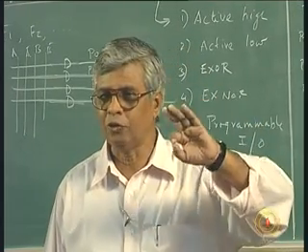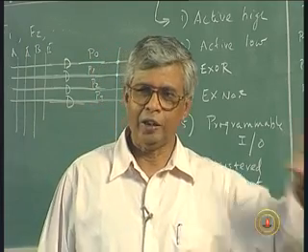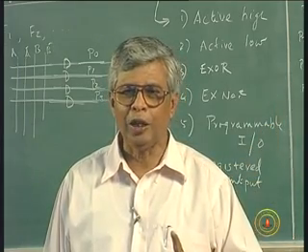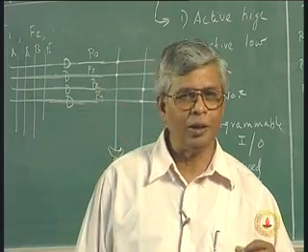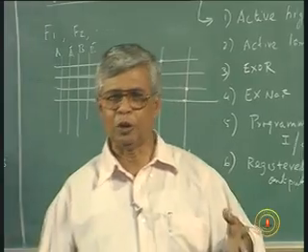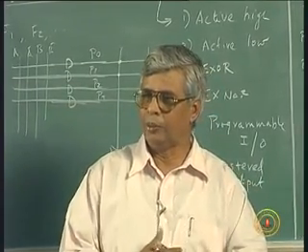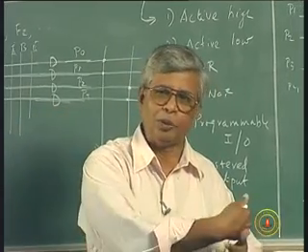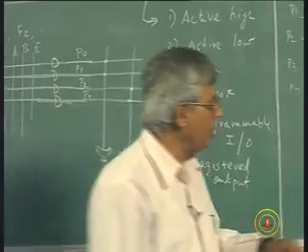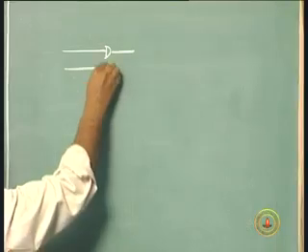Suppose I have a single chip solution for the type of problems we did earlier, sequence detector and all that. We had combination logic, we had flip flops outside. Those flip flops outside need not be put now because these are ICs, small ICs. This is one big IC or large scale IC or medium scale IC, and you want to have extra small scale ICs, so put together, and again those extra logic, putting them together, wiring, all that come about. Oh, if I can push those flip flops also inside the PAL, that is called a registered output. What I mean is, you have these outputs. Give a simple example.